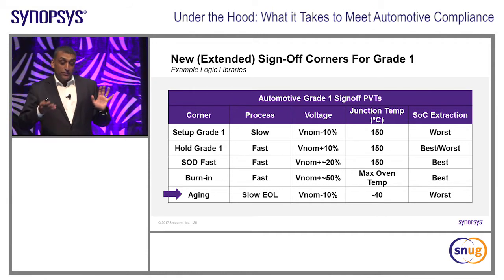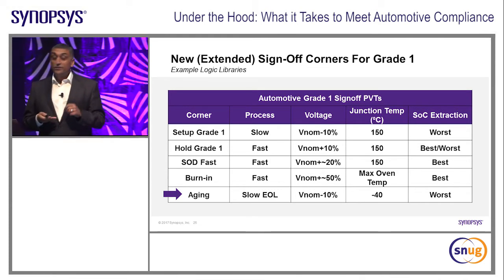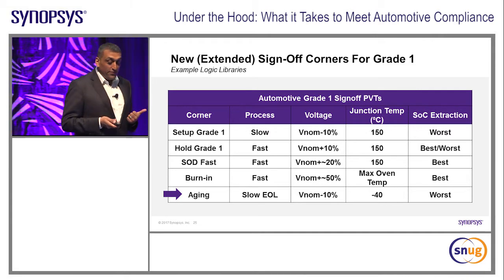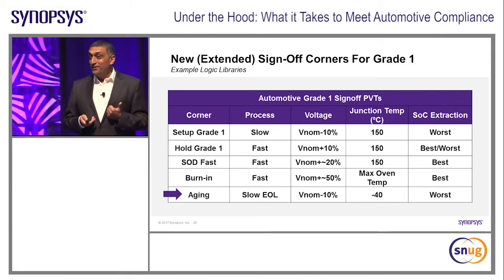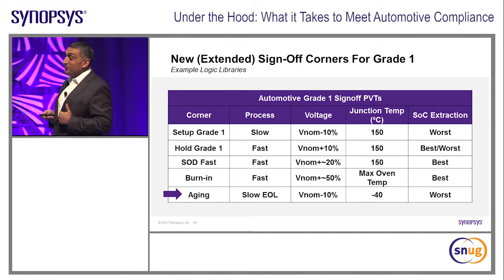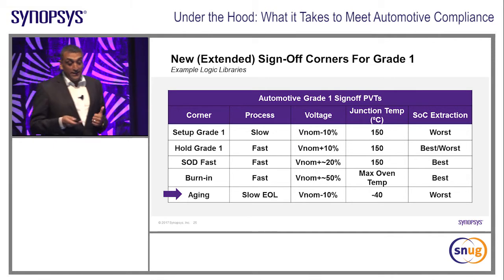However, the reliability requirements of automotive basically tell you not to overdrive transistors, okay? So reliability requirements tell you not to overdrive, and I'm standing up here telling you, actually, we need to super overdrive in order to meet all those real-time processing requirements for your favorite microprocessor that you're using in an ADAS chip.